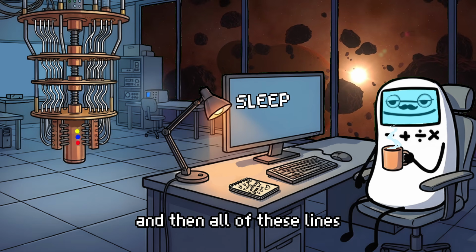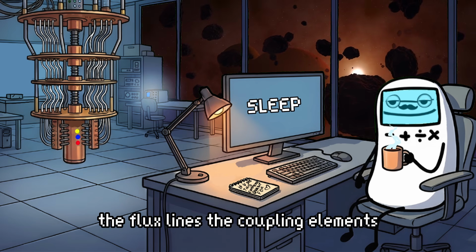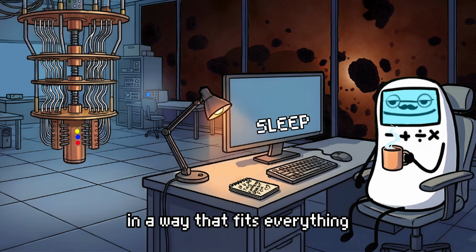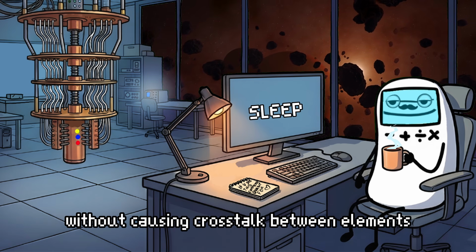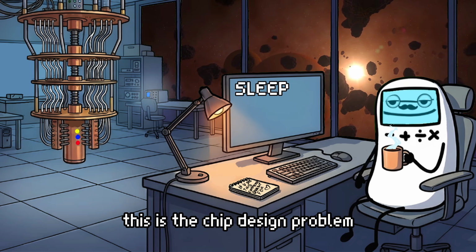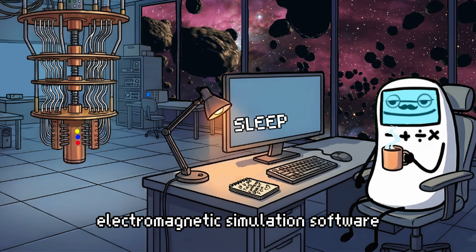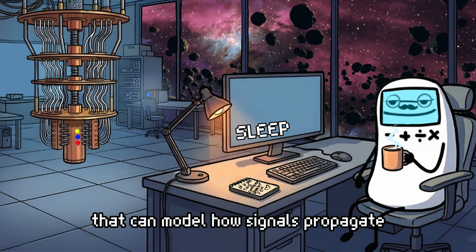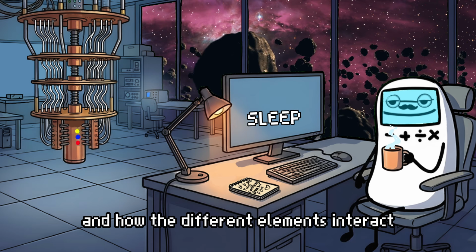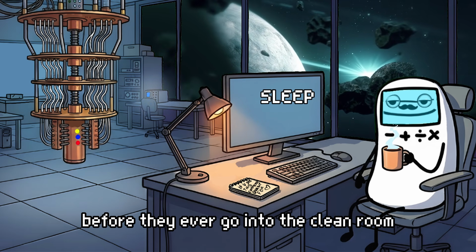And then all of these lines, the control lines, the readout lines, the flux lines, the coupling elements, they all have to be laid out on the chip in a way that fits everything in the available space without causing crosstalk between elements that aren't supposed to talk to each other. This is the chip design problem, and it's done using microwave electromagnetic simulation software that can model how signals propagate through the circuit and how the different elements interact. People spend months designing a processor layout before they ever go into the clean room.